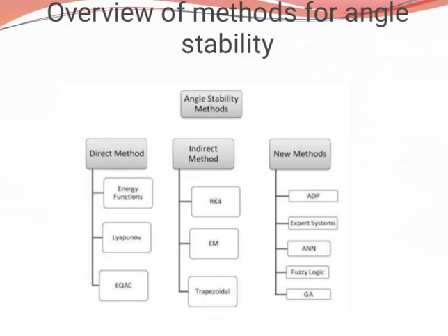In actual system operation, the parameters and the loading conditions are different from the assumptions we made during the planning stage. As a result, to ensure the security of the power system against possible abnormal conditions due to contingencies, the system operator needs to simulate the contingencies in advance, assess the results, and take preventive control action if required. So for that we are going to study these things.